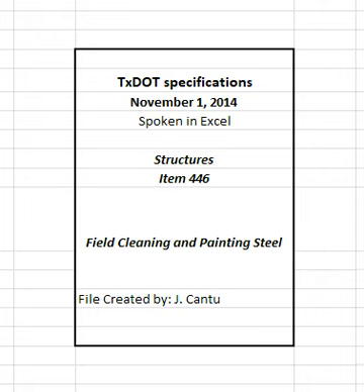Store, characterize, and dispose of all recovered debris in accordance with 30 TAC 335, industrial solid waste and municipal hazardous waste. Alternatively, universal waste rules may be used. Discharge liquids in accordance with the TCEQ Texas Pollution Discharge Elimination Program, 30 TAC 305, effluent guidelines and standards for TxDOT permits, and Texas Surface Water Quality Standards, 30 TAC 307.